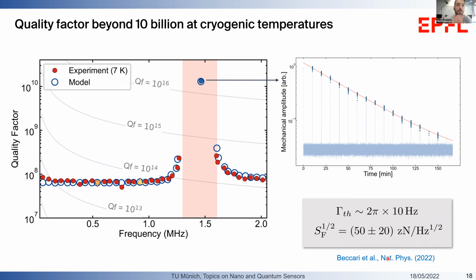Indeed, we were able to observe this kind of enhancement by doing an experiment of pulling down some high aspect ratio strained silicon nanostrings. For this device, the length was about 6 millimeters, and the thickness was about 12 nanometers. Here we characterize the quality factors of the different low order flexural modes, the out of plane or transverse flexural modes, of the nanostring.